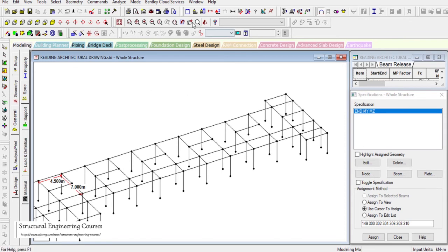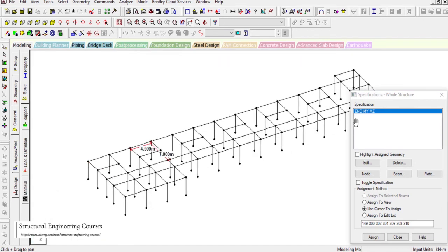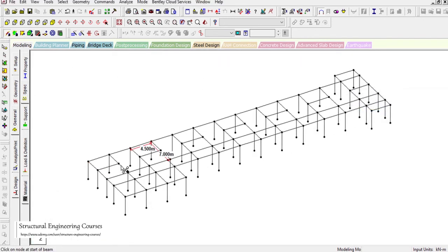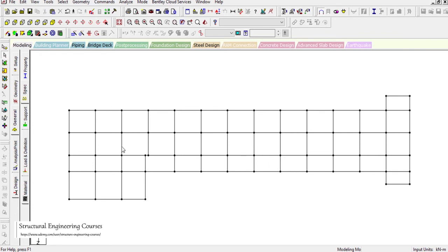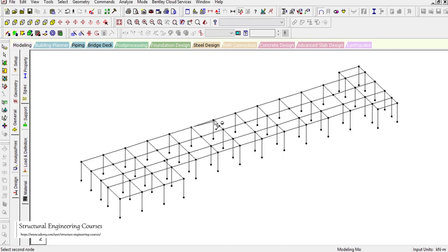By making all the beams here, we can just tie our structure. So now we can see that in the plan view, the spans of the slab are less. That is in the range of 3.5 to 4.5 meters, which is not a very big deal for slab design.